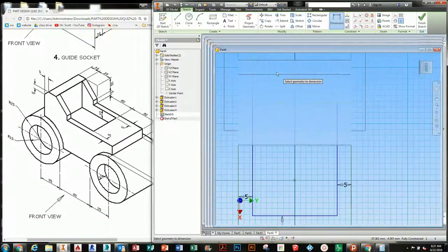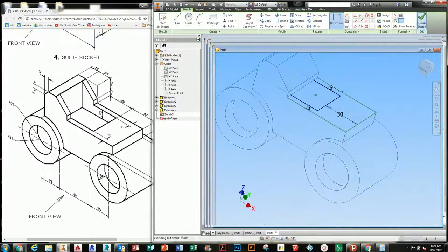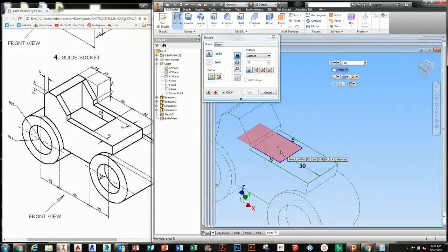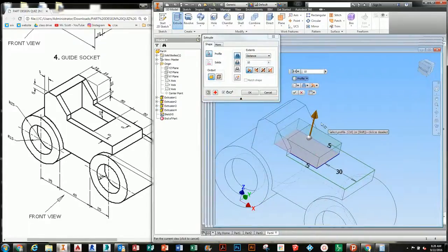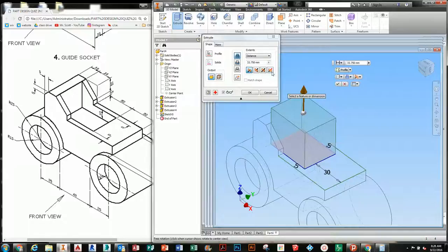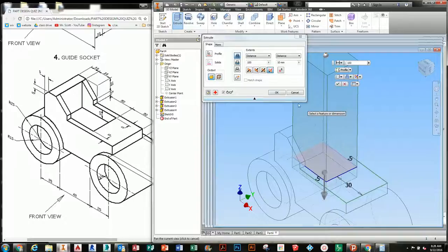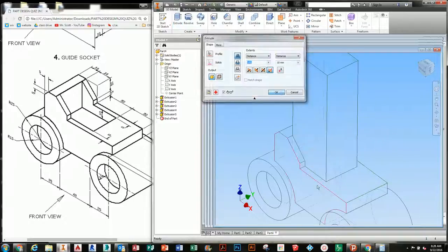And it should be coplanar to this back edge. So notice that the beginning of that chamfer, which is 15 back, should be hitting this back edge. Then what you do is you extrude. We're going to click this object and pull it up, but we're going to do an asymmetrical extrusion. So again, we click asymmetrical, and we're cutting down 10 into the chair, and we're just cutting up to infinity, so it cuts all that out. So let's make one of these 10, and the other one like 100 or something crazy. And then you can say OK, as long as your 100 is going up and not cutting out your object.